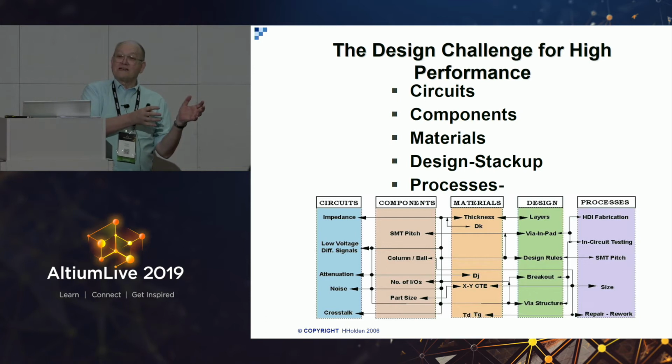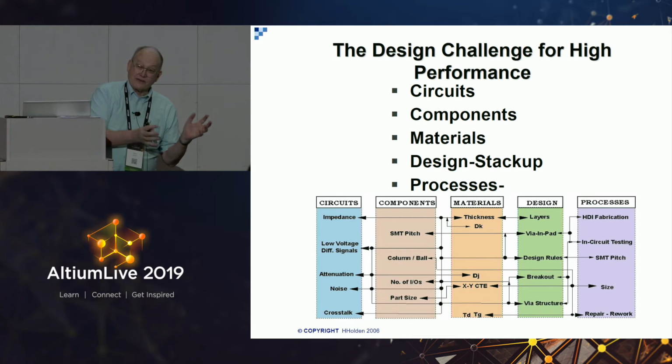But the signal integrity tool ignores that. Well, the dielectric constant and dissipation factor of material changes with temperature, which means that there is an enormous amount of signal integrity error because they don't compensate for the temperature changes that they have access to in their thermal model, but they haven't bothered to integrate the mechanical thermal with the electrical signal integrity.